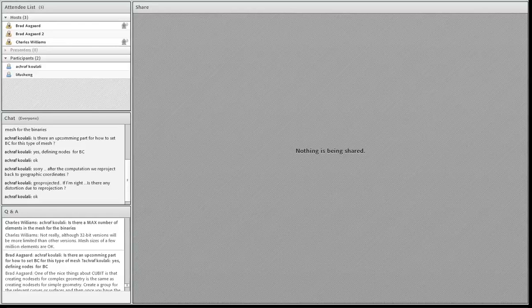I generally prefer to pick a geographic projection that's going to have not much distortion for the particular domain I'm working in, and I pretty much stick with that from the meshing all the way through to the visualization. Sometimes in the visualization I'll switch to a different projection. And there's an example, a two-cell TET4 example. It's discussed in the chapter near the beginning.